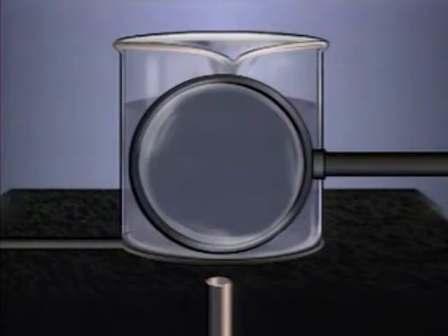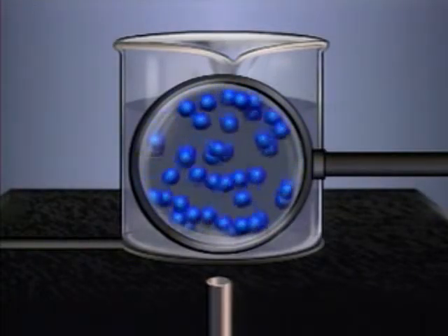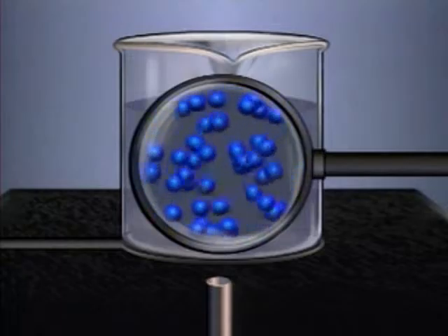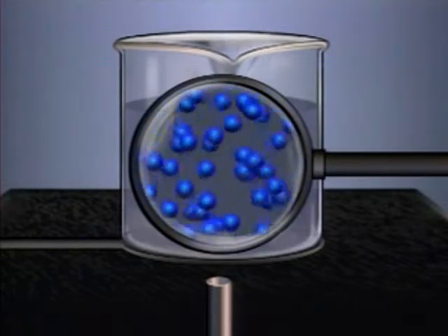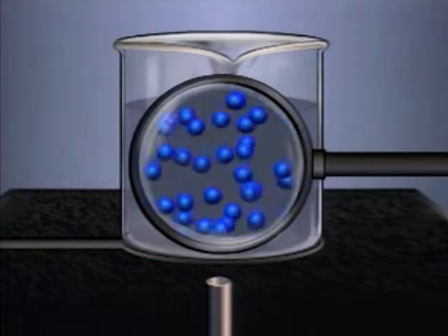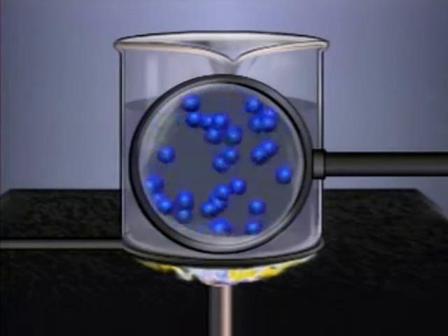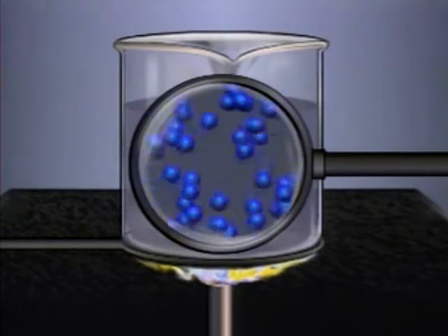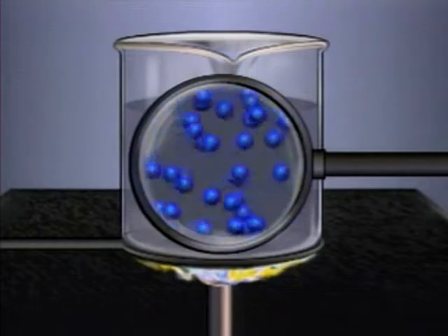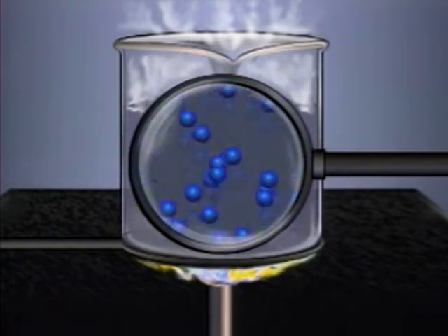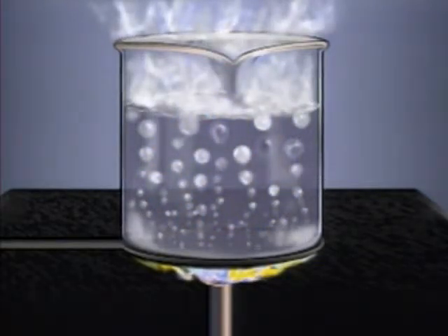Many fluids and process systems are in a liquid state. The temperatures and pressures at which systems operate can have important effects on liquids. In liquids, there are cohesive forces between the molecules, but these forces are fairly weak. As a result, the molecules can move around freely. Temperature changes affect this molecular motion. When a liquid is heated, the molecular motion increases. At a high enough temperature, the forces holding the molecules together are overcome. Then some of the molecules separate from the liquid and are released as a gas. In the case of water, this is the point at which the water boils into steam.